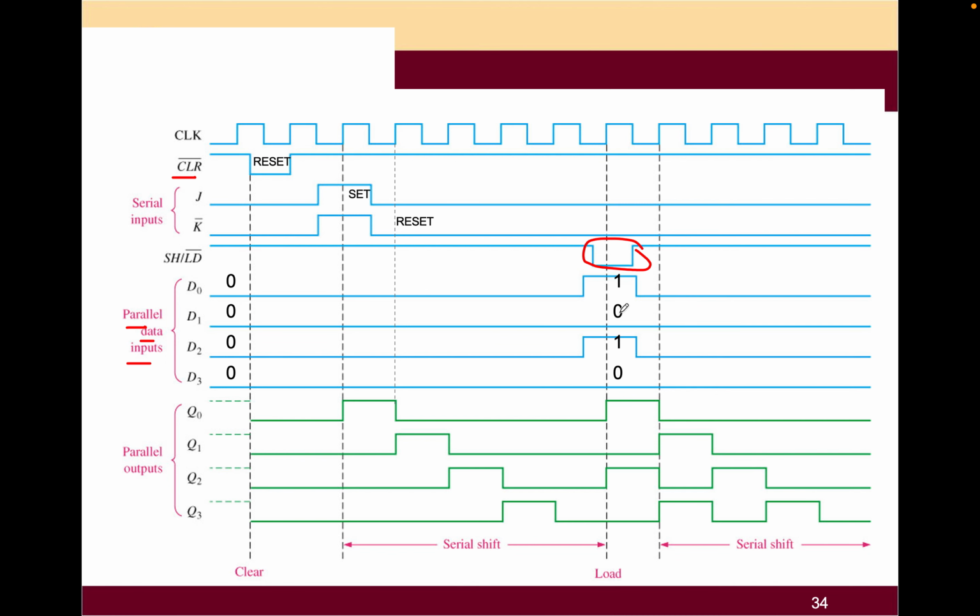So here will be 1, 0, 1, 0. This is your data. Okay, it will look like this: 0, 1, 0, 1. This will be your MSB. This will be your LSB. So now you know one thing, which is the data input. And then you're going to pull everything out after you have a 1 at the positive edge. Then you're going to trigger to pull out.